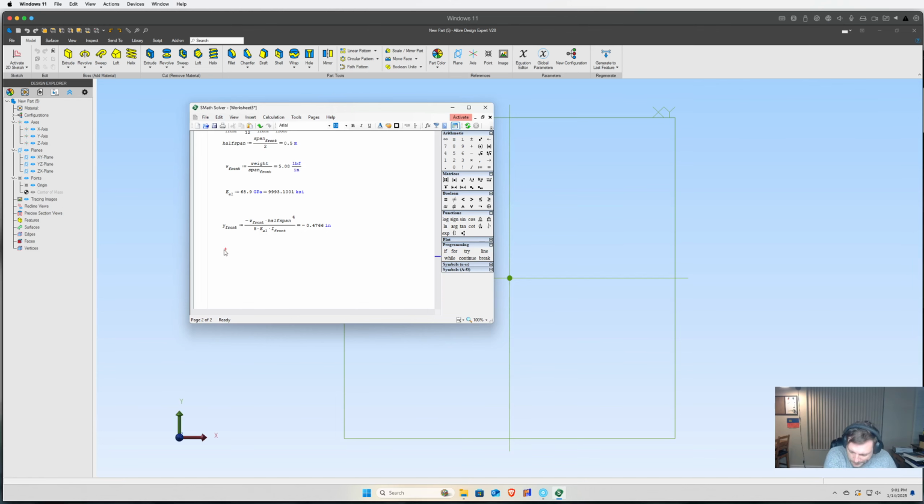And I'll look at the first modal frequency of the front. So that's F1. We'll just call that F1 of the front. And that's going to be something called lambda 1 of the front. And we take the square of that. This is just a formula straight from the book. 2 times pi times the length, which is going to be the half span, squared.